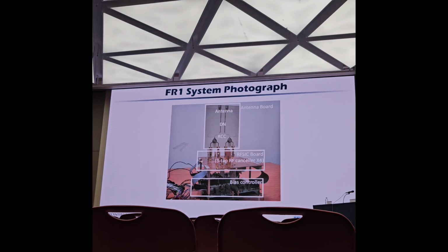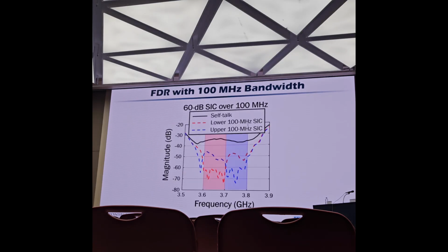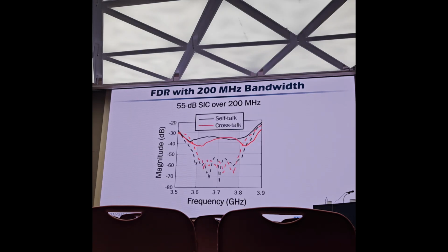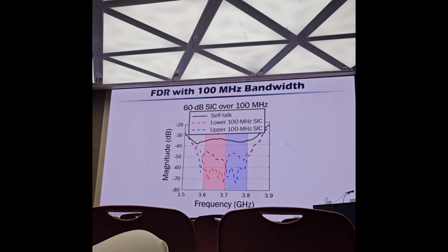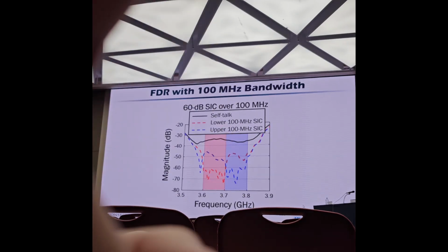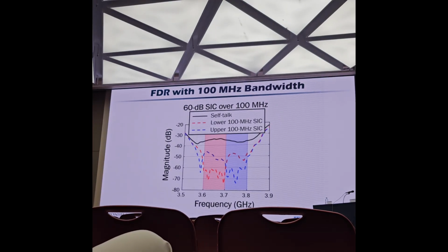These things are the fixed delay filters to have long enough delay. So by controlling all the circuits for the 200 MHz bandwidth, we can achieve isolation of around -55 dB. If we control in a narrow bandwidth, we have higher isolation than what we planned.